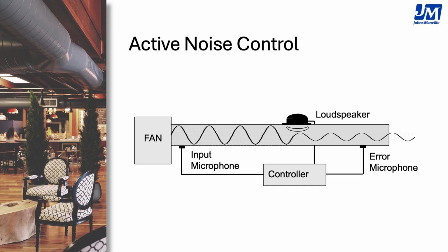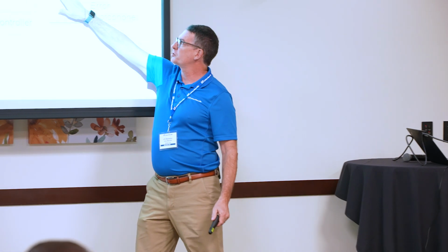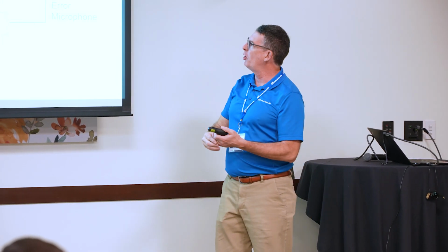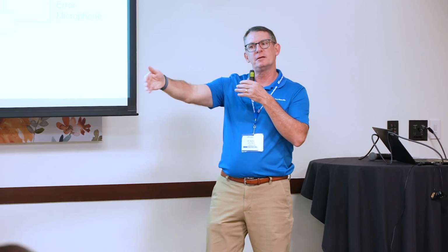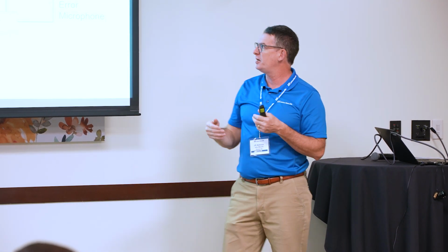It sends out a signal that literally cancels out the sound that comes down that ductwork. I will tell you, this works really well at really low frequencies. The lower the frequency, the longer the wavelength of sound, and the better it stays put. It is well contained by the ductwork.